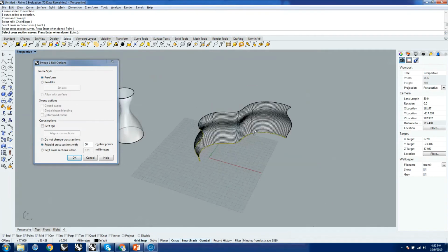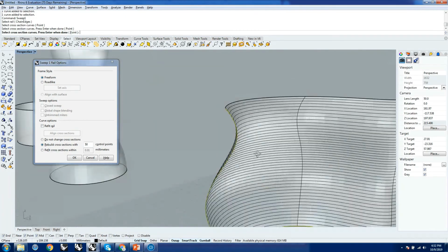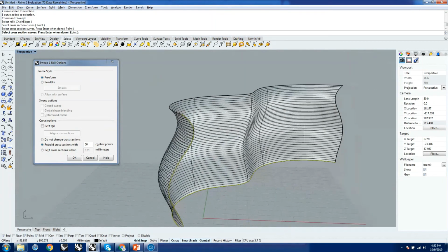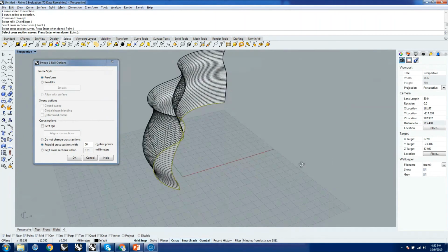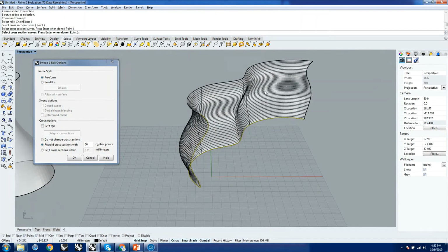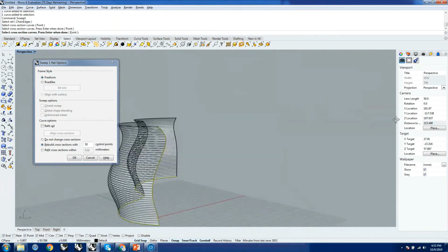So it will have 50 control points, just to give more options. Also, you can see that all these control points have made some really nice and healthy lines and curves. That's because the curves that we started with were healthy. So none of these ISO curves, none of these construction lines that are making the surfaces, are intersecting into each other. You might see this black botch, but that's because of the visualization.